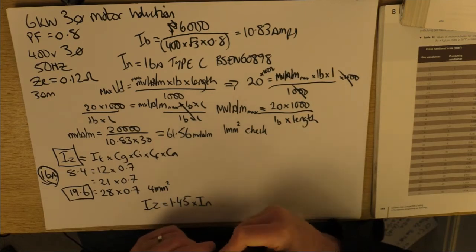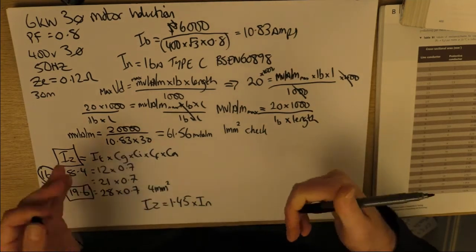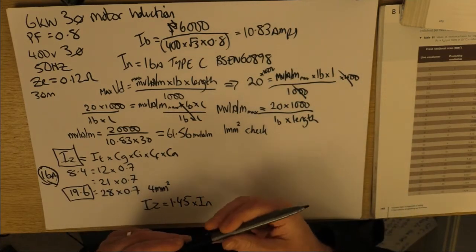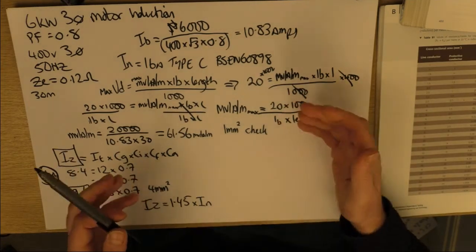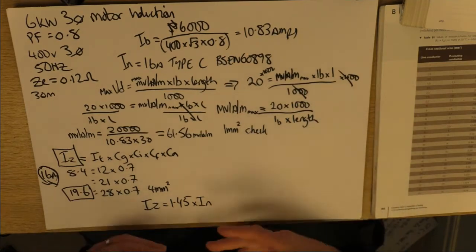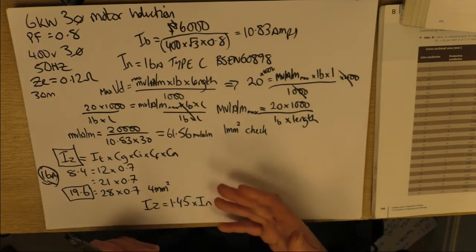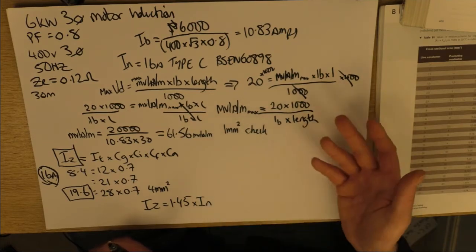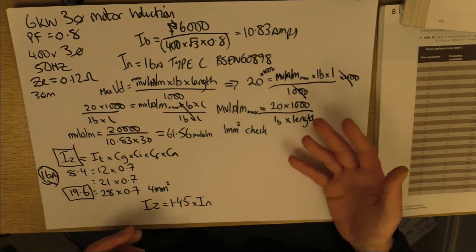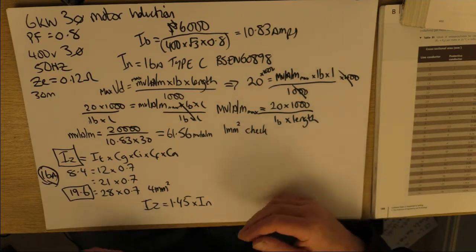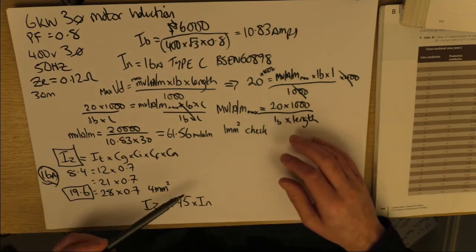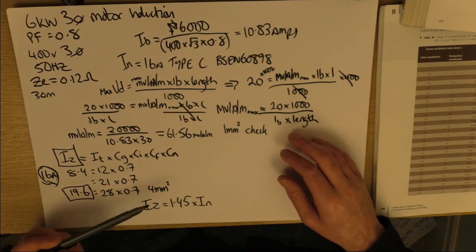And in that time, you might get a problem with the circuit. So it's normally going to be things like socket circuits, where you don't really have a lot of control or knowledge about what they're going to plug in. So places like care homes in the winter, you know, they're going to pull out all them heaters, they're going to plug them in. Same with meeting conference centers, places like that. We don't know what they're going to turn up with. So, you know, you need to consider this.